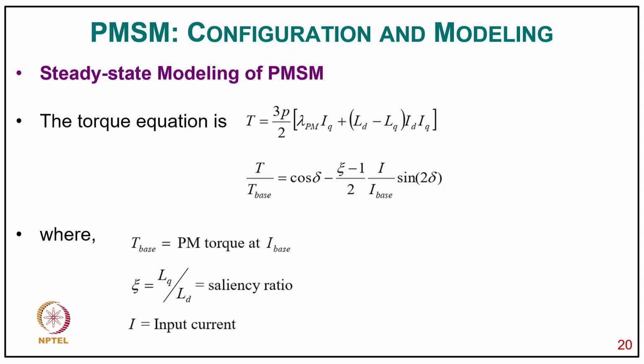And in this expression, you can clearly see an interesting feature: the second term is responsible for below base speed. We can increase the excitation by introducing the value of ID, and by going above base speed, we can introduce the ID value with the opposite sign, and that does the field weakening. So that's very useful for electric vehicles with a high starting torque, and then to get a constant power characteristic over a wide range for very high speed.